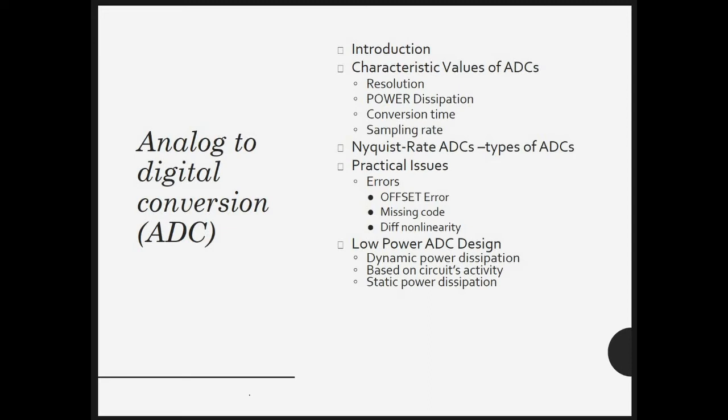While a microprocessor can analyze analog data, it must be converted into digital form for the computer to make sense of it. The conversion involves quantization of the input, so it necessarily introduces a small amount of error. Instead of doing a single conversion, an ADC often performs the conversions periodically. The result is a sequence of digital values that has been converted from a continuous time and continuous amplitude analog signal to a discrete time and discrete amplitude digital signal.